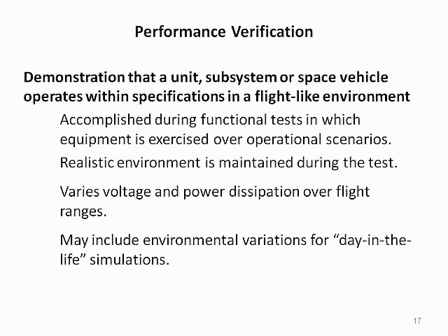Performance verification demonstrates that a unit, subsystem, or space vehicle can operate within specifications in a flight-like environment. Functional tests are performed in which equipment is exercised over operational scenarios during the temperature plateaus and transitions. A realistic temperature and vacuum environment is maintained during the test, plus applicable margin.